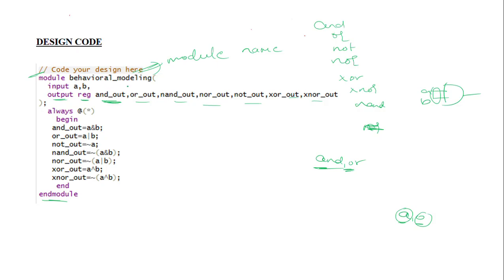Now in behavioral modeling, what does always mean? Always means every time. As the keyword name itself says, always. Then at the rate, and what is inside the bracket, we call it the sensitivity list. Whatever you write in these brackets is the sensitivity list. It means if there is any change in the variables we represent there. For suppose if you write A comma B in this sensitivity list, these are the variables used to define when the block executes, whenever the values in these brackets change.